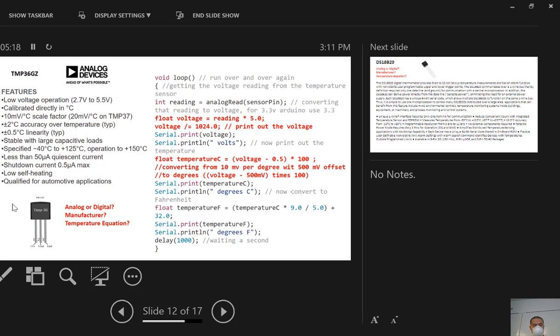And there's another type of temperature sensor, which is a semiconductor based temperature sensor. That material changes the resistance when the temperature changes, and then it is able to output an analog voltage. You still have to follow a certain equation from the data sheet to convert that voltage output. It's an analog output. Keep in mind, this temperature sensor looks like a transistor, but it's actually a temperature sensor that outputs an analog voltage for you to convert into a temperature.